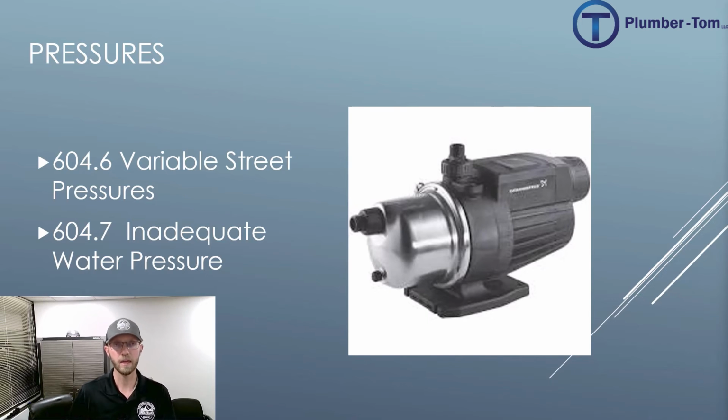So basically, you get a booster pump and you push it to a pressure that works at the fixtures. I've seen city pressures in some locations that are at 25 psi. That's worthless. Your fixtures just won't run. So there's a different design on those houses. Particularly an enormous storage tank with a booster pump that can then pull as much as necessary at the time and deliver at the pressure needed.